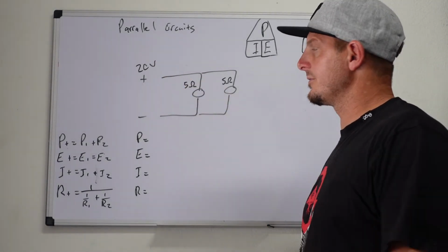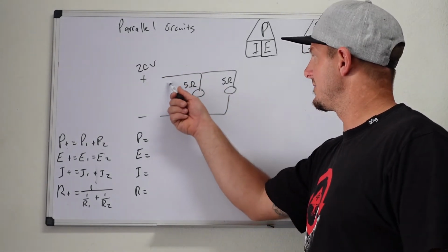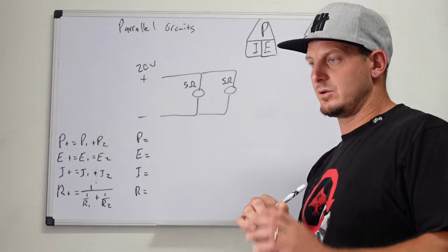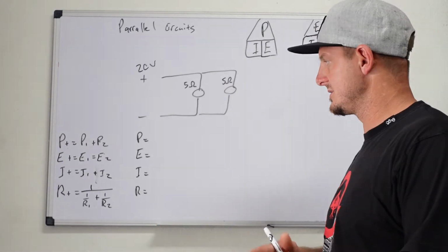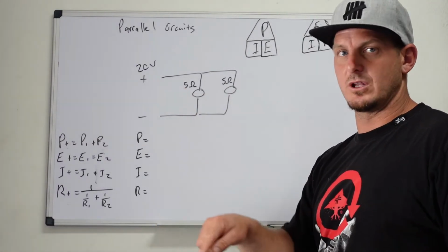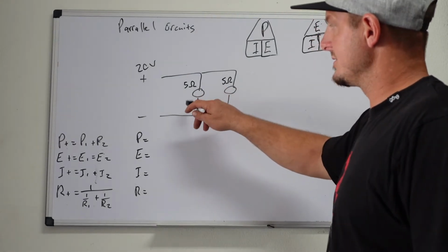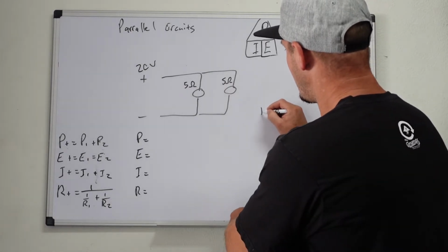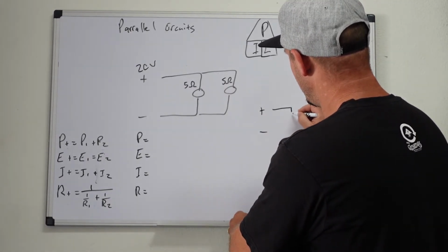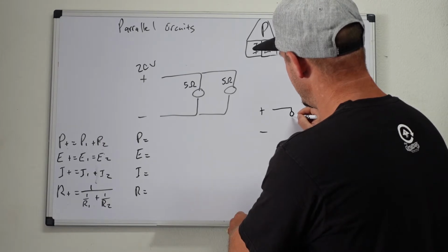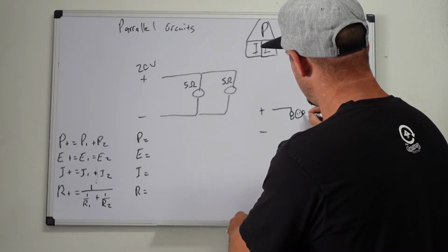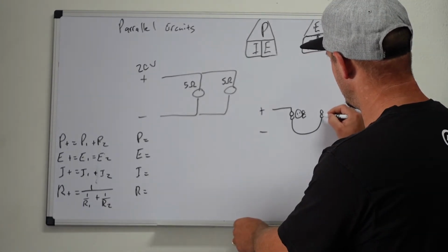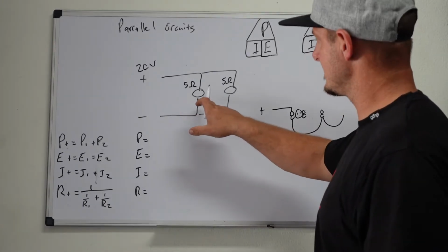Parallel circuits differ from series circuits in the fact that they have more than one path. A series circuit is only one path. You can add as many loads as you want, but it can only take one path to go through those loads. The way we wire receptacles is here, right? Because if we come off our hot wire, we tie it together and pigtail it off one and take it to another receptacle, where we then pigtail it again using the screws to another one. That is essentially the same thing here.